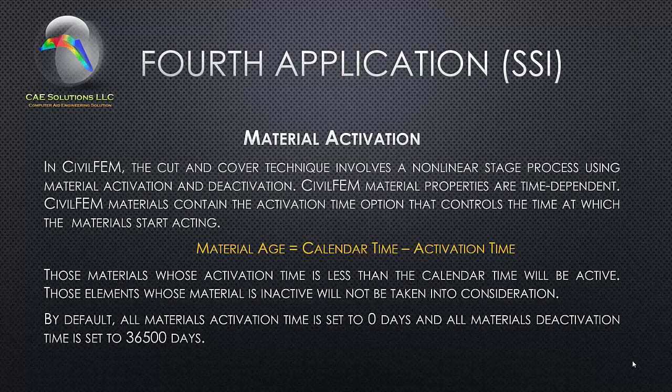Those elements whose material is inactive will not be taken into consideration in the formulation of the model, the stiffness matrices. By default, all materials activation time is set to 0 days, and all materials deactivation time is set to 36,500 days. So that will be 100 years.